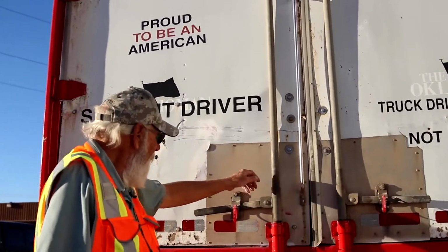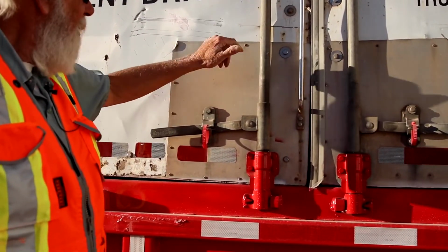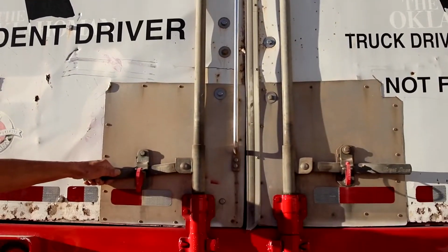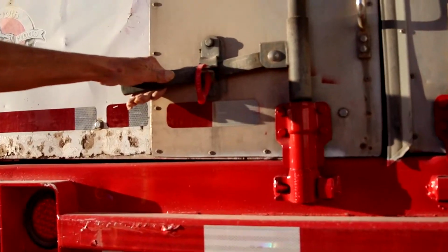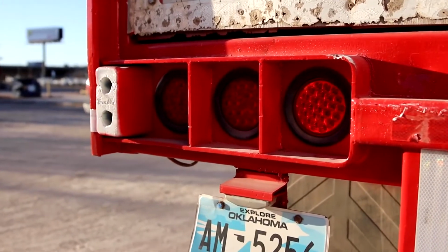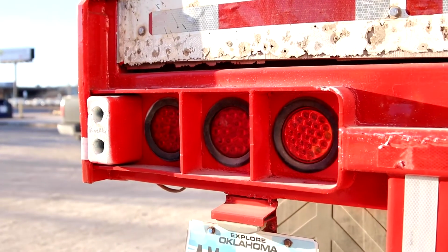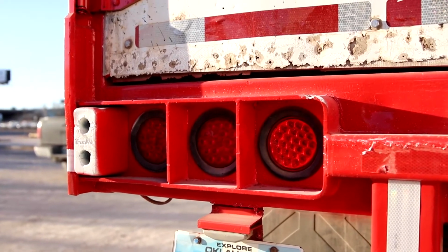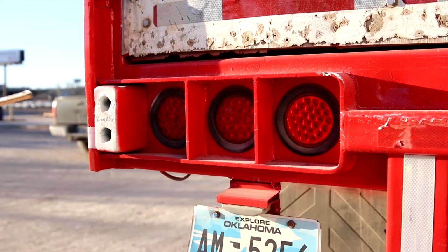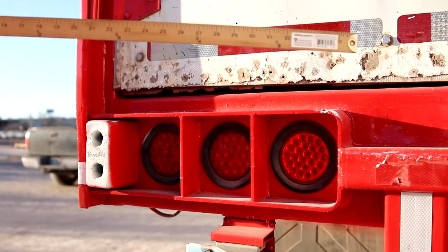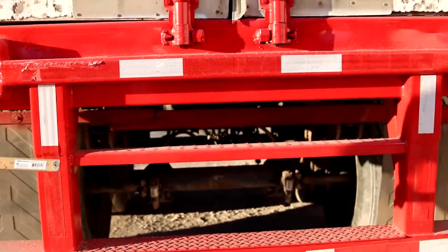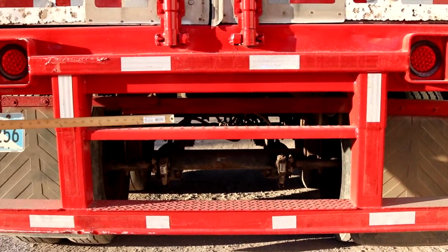These are your door latches. Make sure the doors are shut fully, top and bottom. And these are your door safety latches. They are locked into place, top and bottom. Then, moving to here, you have your brake lights, tail lights, turn signals left and right, 4-way flashers, and park lamps. Red in color, not missing, damaged, or broken. 100% DOT tape across your DOT bumper, and your DOT bumper is not damaged or broken.